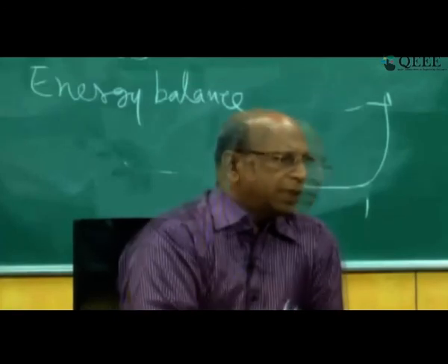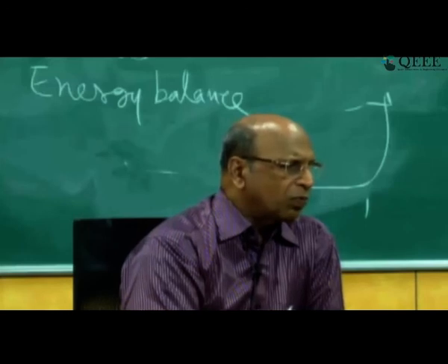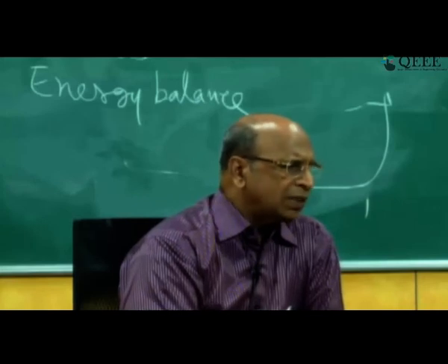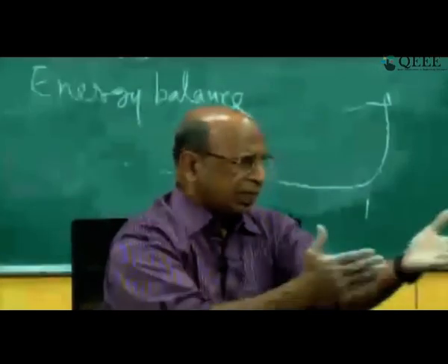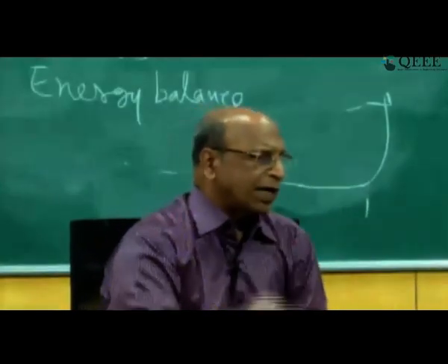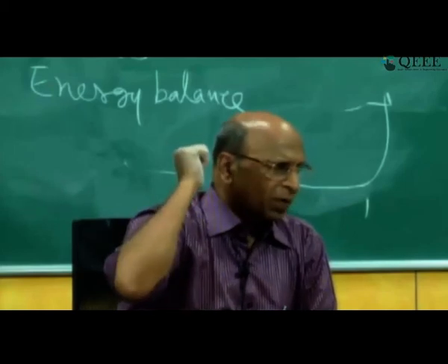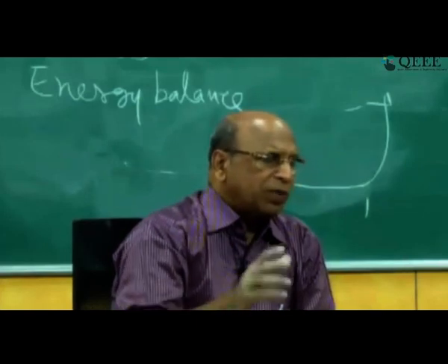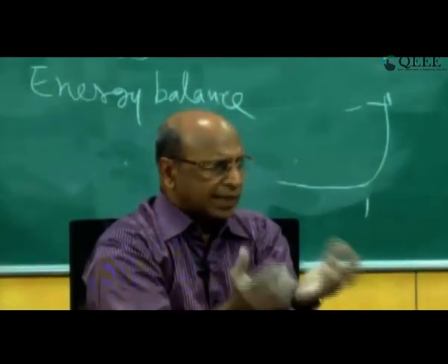Okay, good. Is the performance equation for fed batch the same as that of MFR? Okay, both cannot be the same. I think the operation itself is different, right? We are talking about mixed flow reactor which we derived. We are talking about fed batch reactor where we have not derived. If there are two reactants, one reactant can be taken in the reactor itself.